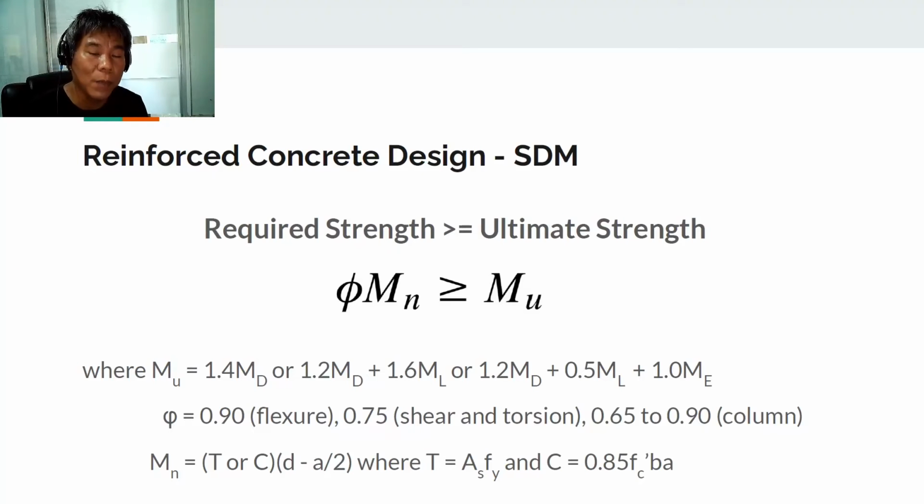of the beam. So here, if you have the ultimate moment and then you have the strength reduction factor, also you have Fy and the dimension of the beam, you will be able to determine the number of rebars. So that's how we do the design, the proportioning to determine the size of the section and the number of rebars.